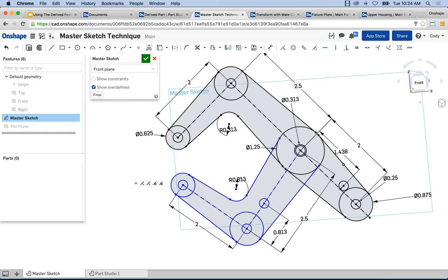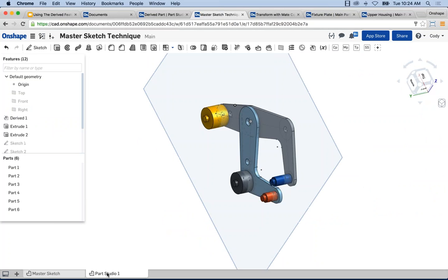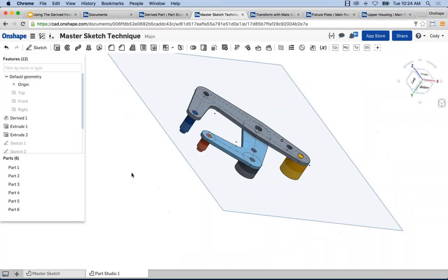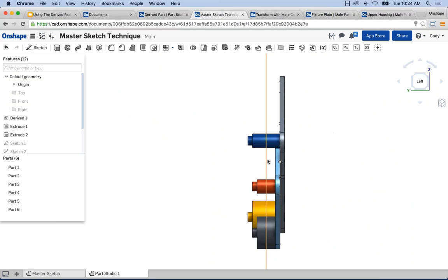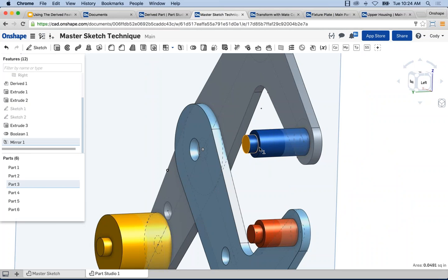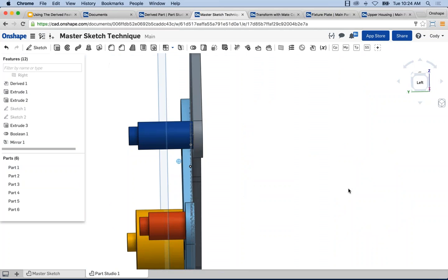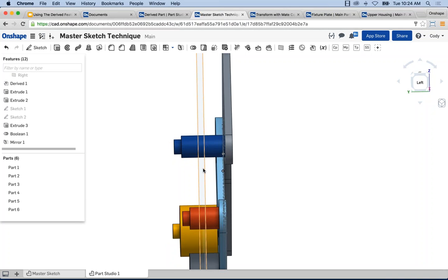Remember, everything's in one document, so it's going to instantly update. I go back, everything instantly updates. Okay. And it's not just that. Let's go to the left plane here. I can also change the plane location in the original. So let's do a quick measurement from end to end here. Face to face, we have a measurement of 1 inch. And let's say I needed the gap between these clamp arms bigger. I need to change the offset of this plane.